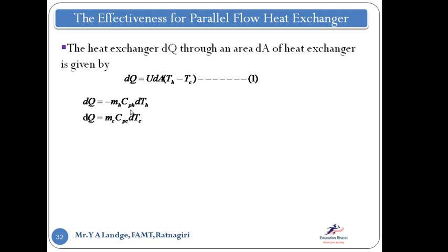After that we write these equations. One equation is for the hot liquid and another is for the cold liquid. The differential heat transfer rate is equal to minus m_h c_ph dTh, the differential temperature. And dq is equal to m_c c_pc dTc.